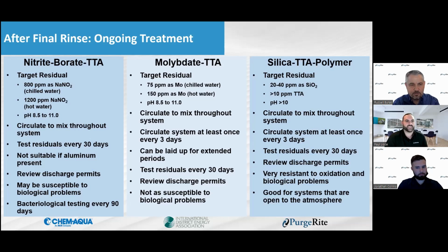And there's ways when you're testing: if your conductivity remains consistent, but you're losing nitrite ppm, well, then it's being consumed by microbiological growth. Whereas if you have conductivity drop and nitrite levels drop, then you're losing water. So that's one easy way of telling. But you could also do microbiological analysis, anaerobes, aerobic bacteria, IRB, SRB, on your system to make sure that it's fully sterilized and you're not having any kind of issues.